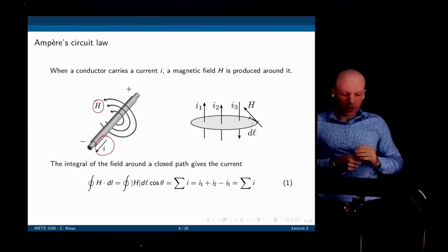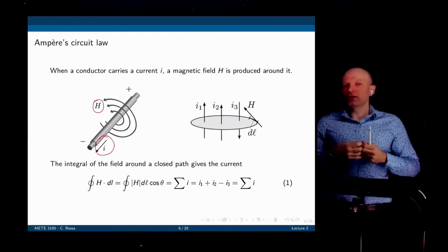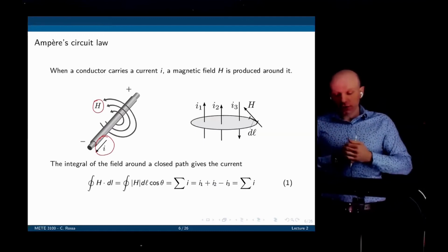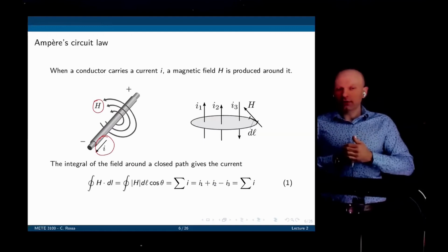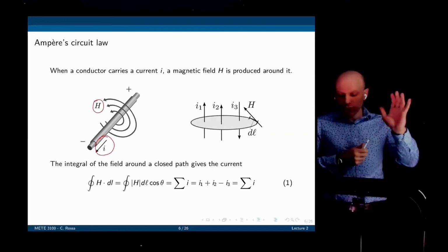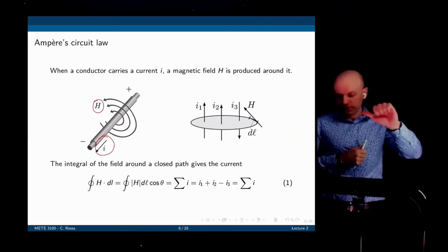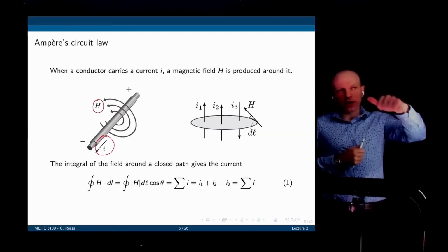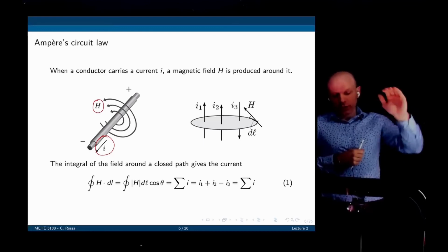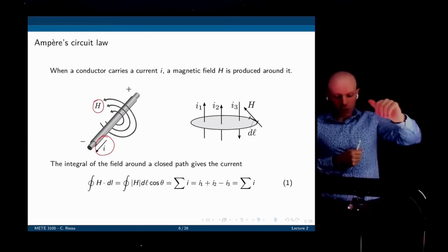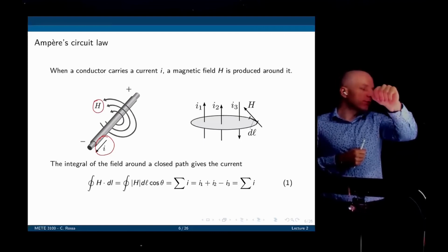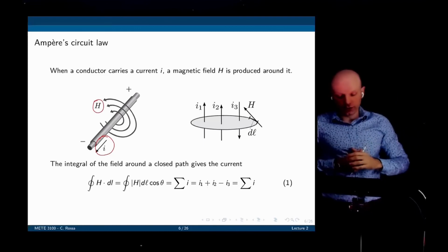And the magnetic field that we have here, called H, is the notation for the strength of that magnetic field. We have this conductor carrying the current that creates a magnetic field, and you can now see in which direction that magnetic field rotates by simply using your right hand. So put your thumb towards the current and curl your fingers around the conductor. In this particular case here, the magnetic field rotates counterclockwise. See, the current goes that way, and then my fingers will give the direction of rotation of the magnetic field.